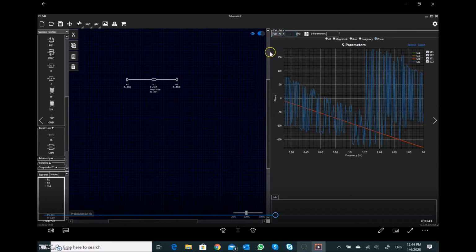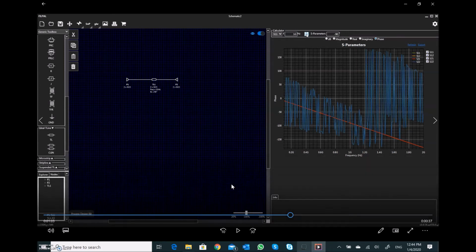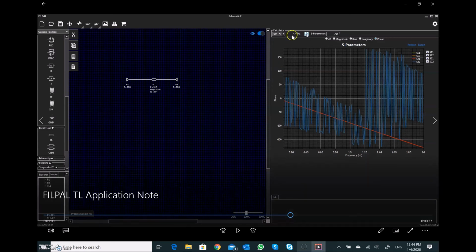And here is a special feature that FieldPower EDS has, which gives you the advantage of simulating the response at particular frequencies of interest without going through a long simulation time. If you still remember, when you go to the settings page to specify the step frequency or the number of points to be run, just in case you've missed some particular frequency points, you may define it here, simulate, and get the exact values at those particular frequencies.